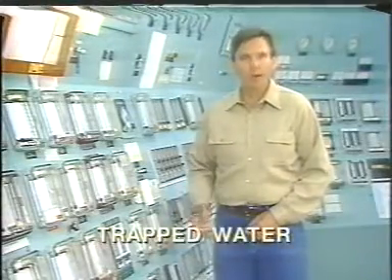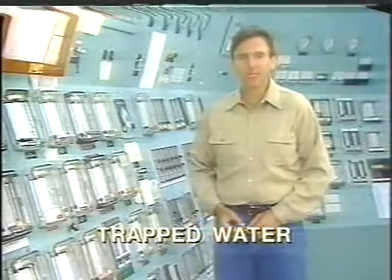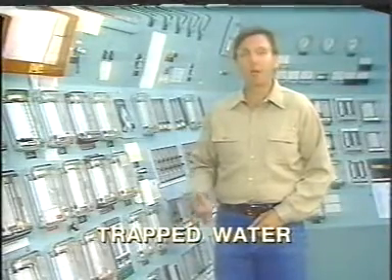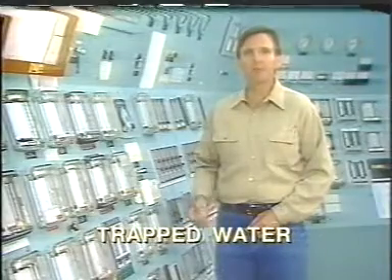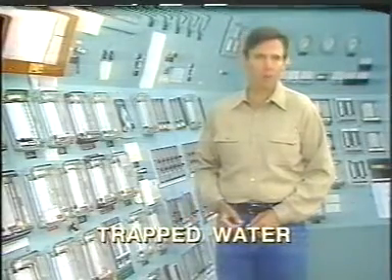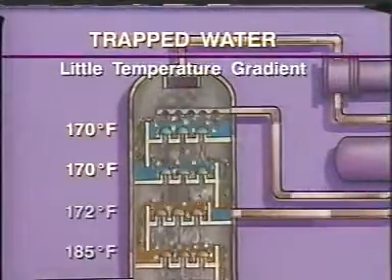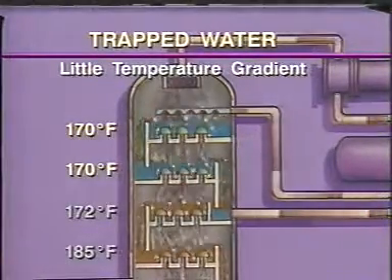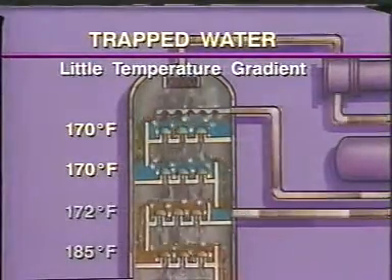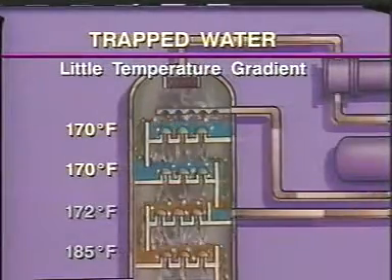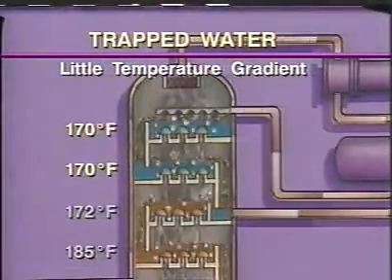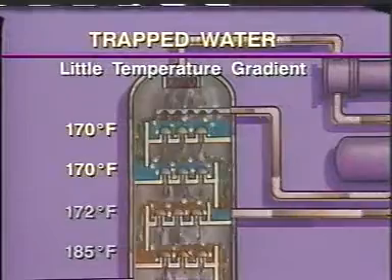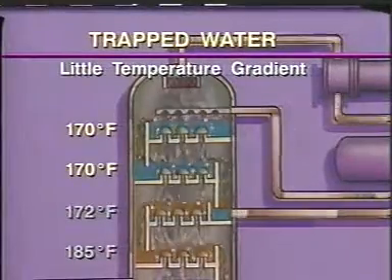Abnormal operations can also be caused by water that inadvertently enters the system. The water may come in with the feed or accidentally through a pump line and gets trapped in an area of the tower where the temperature is below the boiling point of water. Most hydrocarbon streams are lighter than water, so they float on top of it. When a section of trays becomes filled with trapped water, fractionation in this part of the tower stops because there are no hydrocarbons to make contact with the upward rising vapors.